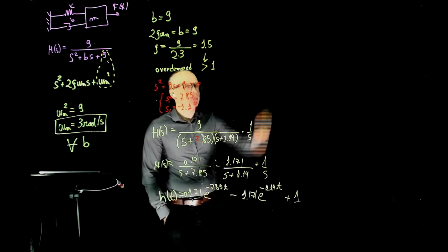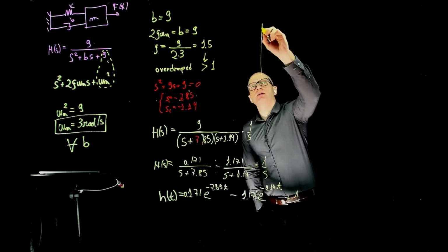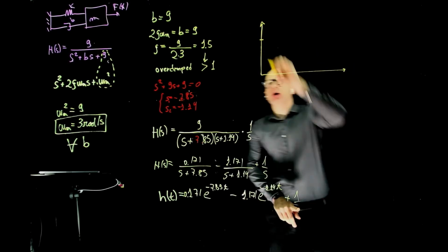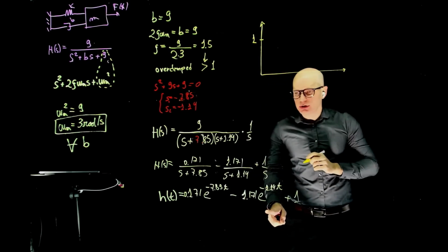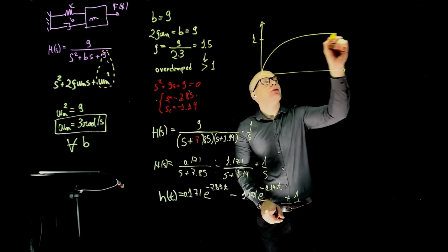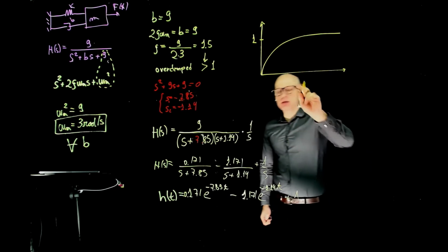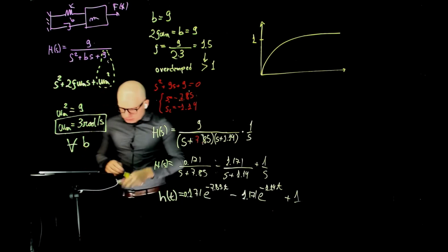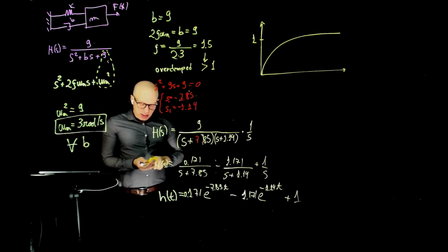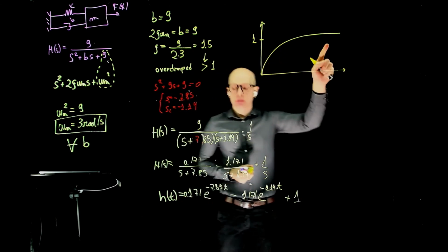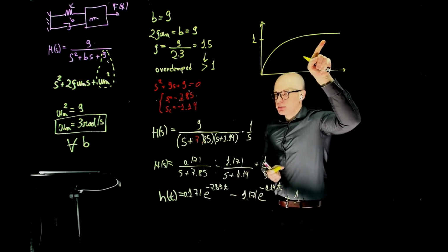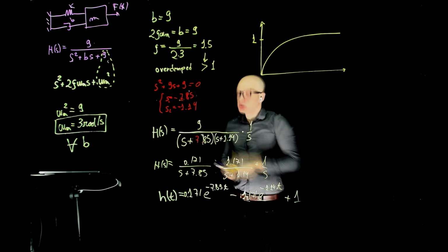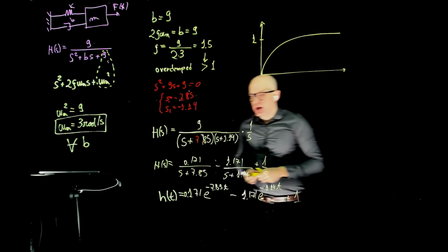If we plot the time response, what should we see? We should see the system tending to 1. Remember that these two terms will eventually die to 0, and it goes to 1 following an exponential waveform. This precisely characterizes what we defined as an overdamped system. Everything agrees. The system is overdamped, meaning that it only has an exponential component. This occurs because the poles are real numbers and the poles have negative real parts, which comes from the fact that the damping ratio is greater than 1.